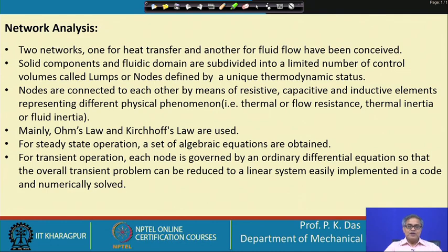And then there is a fluidic network. See, the fluidic network, the fluid inside the porous medium, that is again not stationary, that moves from condenser to the evaporator, and then in the core region of the heat pipe there is the vapor which flows from the evaporator to the condenser. So, these two fluids, they constitute your fluidic domain.